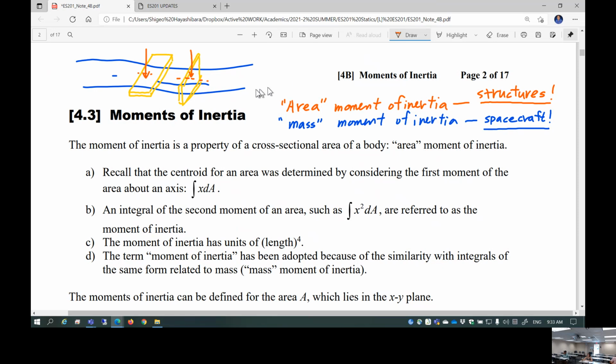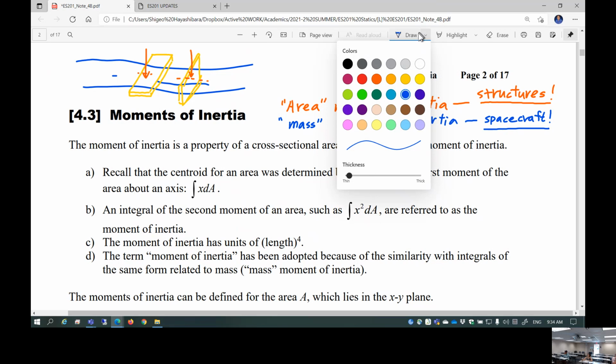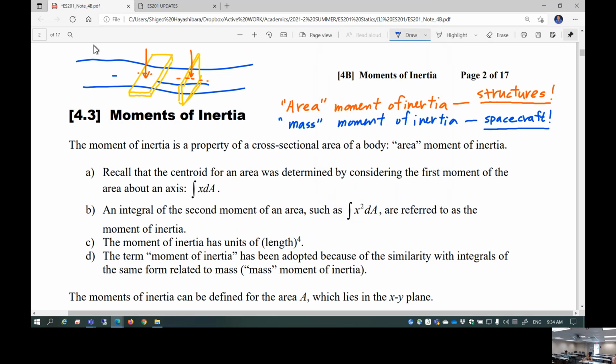What is the big difference between those two? The difference is moment of inertia: how much area is distributed away from the centroidal axis so that you resist the bending, which is maximum at the center of this material. So what is the optimum solution? If you are a serious engineer, you're going to pick up an I-beam or something like that, and make a bridge out of it.